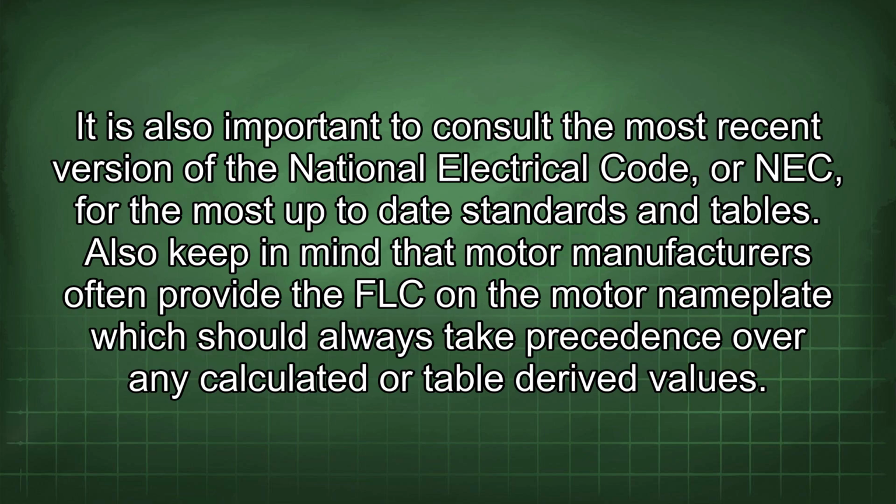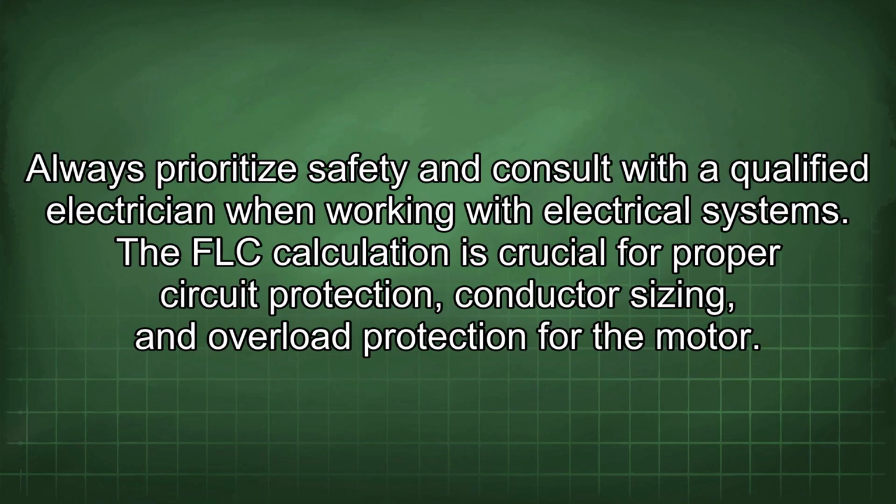It is also important to consult the most recent version of the National Electrical Code, or NEC, for the most up-to-date standards and tables. Also keep in mind that motor manufacturers often provide the FLC on the motor nameplate, which should always take precedence over any calculated or table-derived values. Always prioritize safety and consult with a qualified electrician when working with electrical systems. The FLC calculation is crucial for proper circuit protection, conductor sizing, and overload protection for the motor.